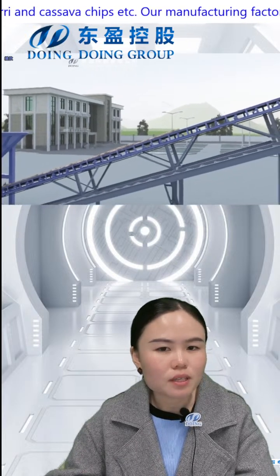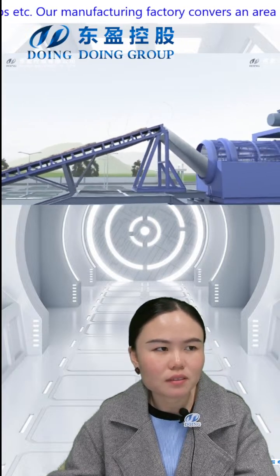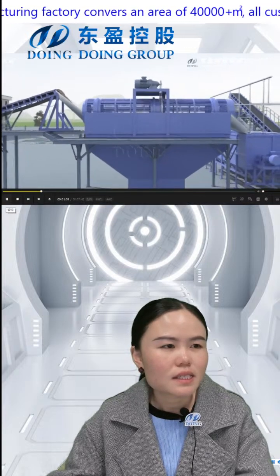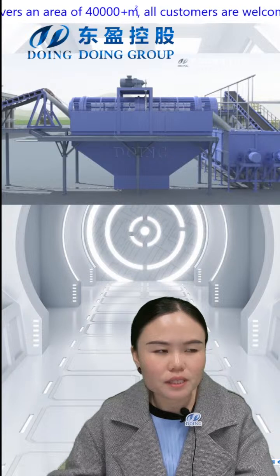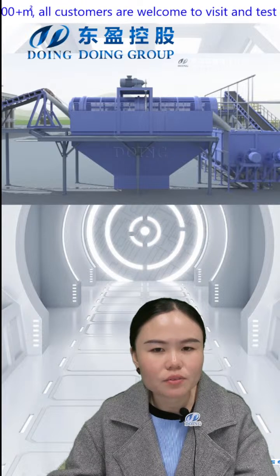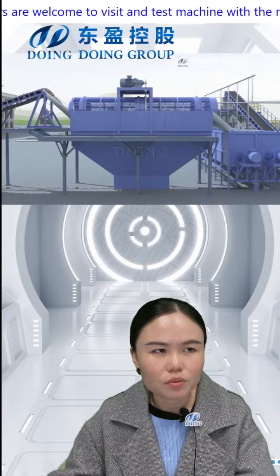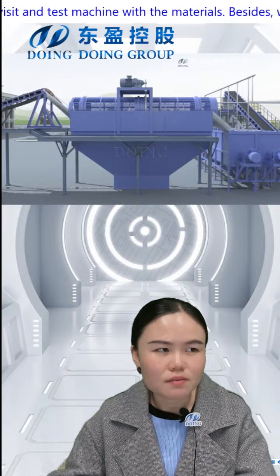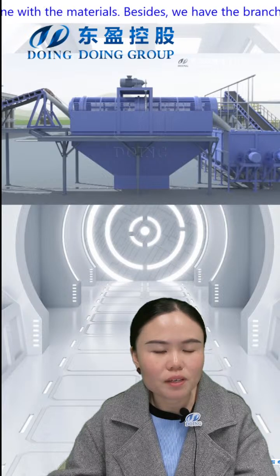And then the belt conveyor will transfer cassava to the dry sieve machine. This is a dry sieve machine. It's used to remove the impurities attached to the cassava surface. When it's running, the friction between cassava roots and the machine will remove the surface impurities like soil and dirt, which will drop down and be collected by the hopper installed below.